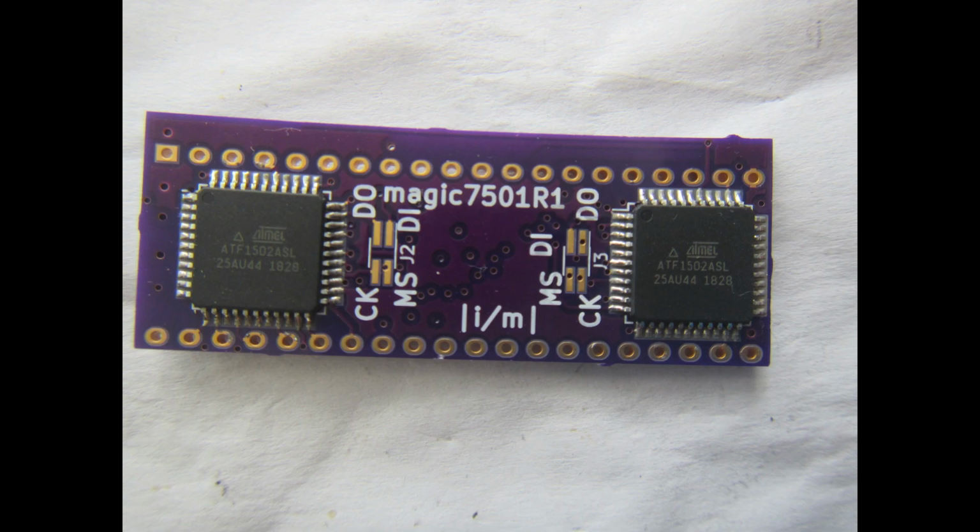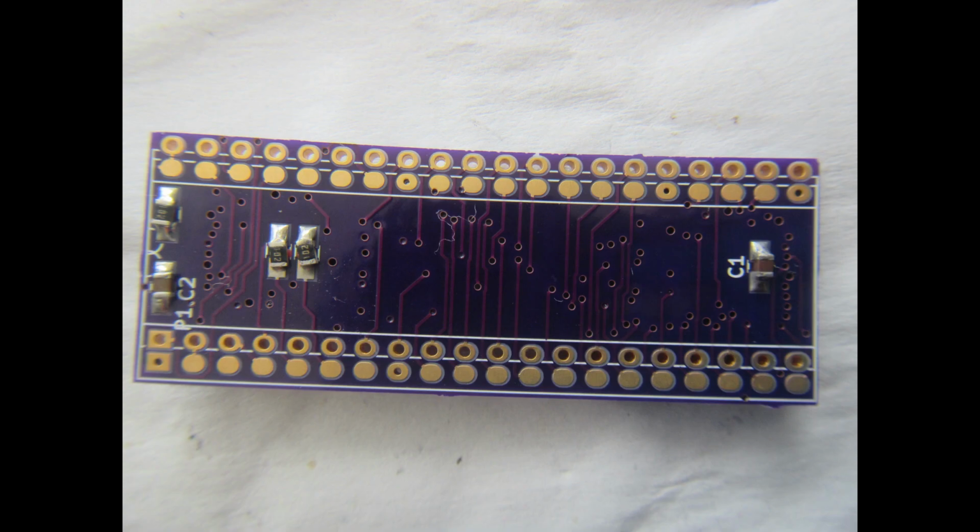I started by soldering the two CPLDs. By the way, 4-layer PCBs take really a lot of heat before the tin melts properly. This is even worse when 2 of the 4 layers are almost all solid copper, like I did in this case, to have one full layer for VCC and another for ground. On the other side, there are just a few resistors and bypass capacitors that need to be soldered before the